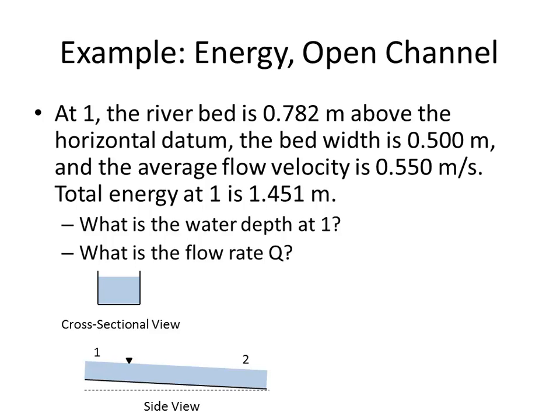We're going to use principles of energy like this when we try and predict the hydraulic jump. The hydraulic jump is what happens in that flume when water flows under a gate at a velocity faster than it really should be going under steady, uniform conditions. So we're going to have hydraulic jump day later in the semester and try and predict what the different depths are that the hydraulic jump will go up to. And all those calculations depend on us calculating energy at different points. And energy is the sum of the flow depth, velocity head, and elevation above some datum.